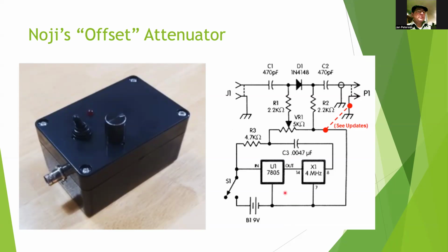It looks like there's no real tuned circuit on the output of that thing. Right. So you could probably go any multiple of 4 megahertz. Yes. And get lower and lower as you went. So if the signal's at 144, you can get it at 148, 152, 156, and the farther you move away from it, the more attenuation you're getting on a logarithmic scale, right? So, yeah. 6 dB per octave.